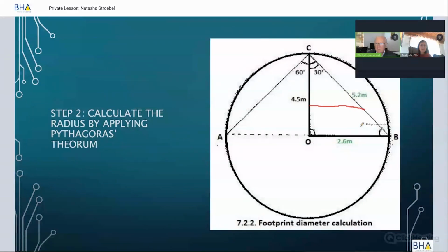All right. So you've done the calculation already, but all you do is you do the calculation for a different height. And that height is the pump island height, and the height to the face of the meter on the pump. So you take that away from the 4.5 and it leaves you with 3.16 of a meter.